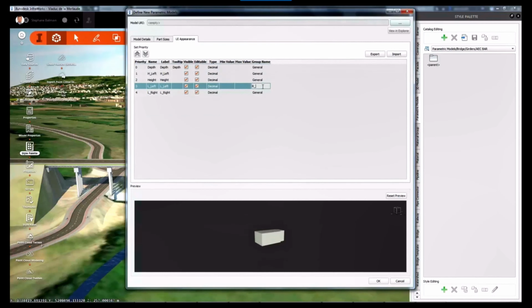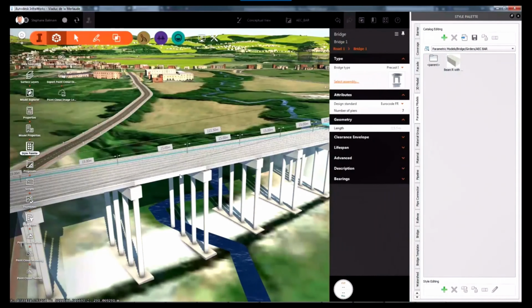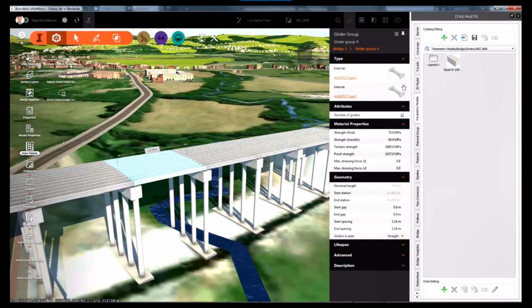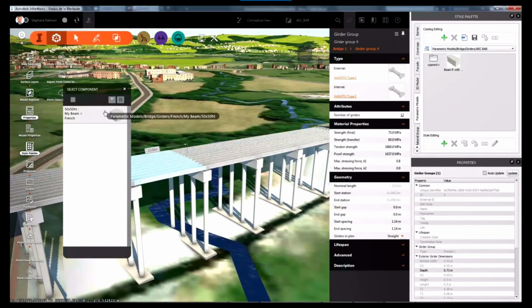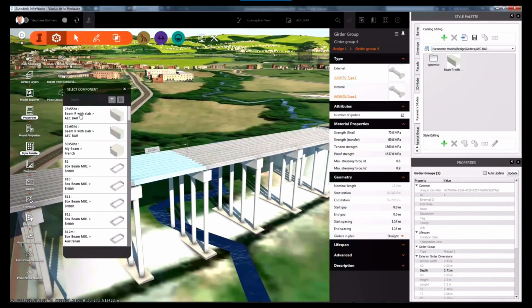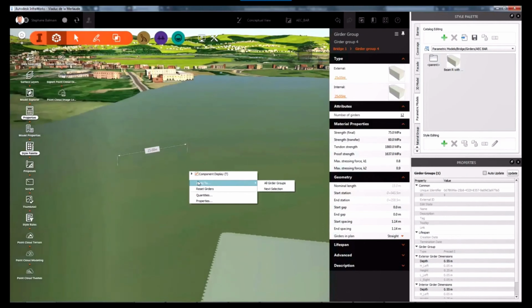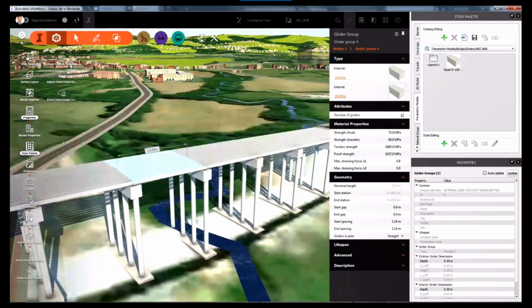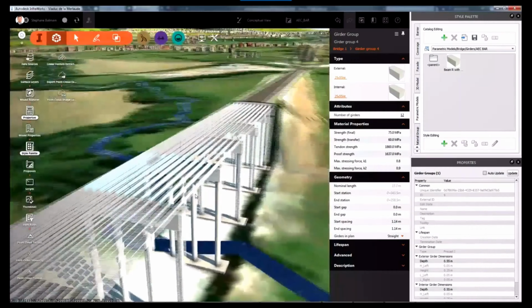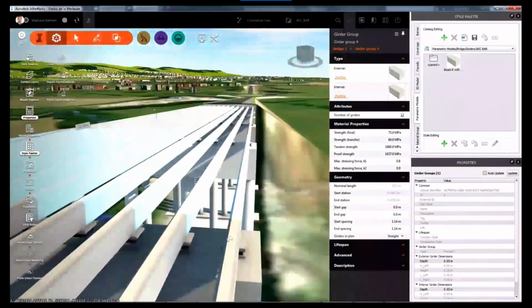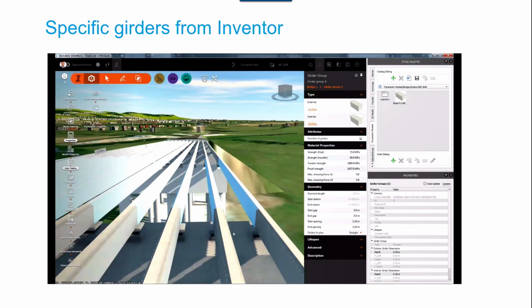And after, the parameters, I can group them to separate them and modify them easily. After, I move my H2 bridge to this BIM. So I will apply it to all the girders in every span, like this. And after, you can see I have the reservation for the precast slab.